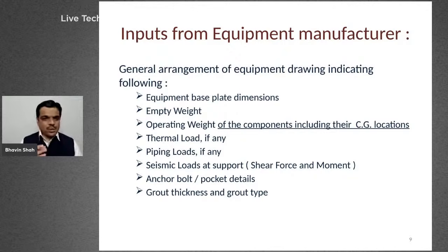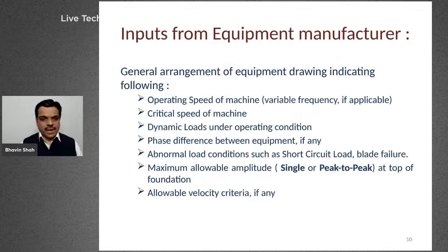And of course, grout thickness and grout type are also very important parameters that will be included in the manufacturer's drawing, and if they are not included, then we discuss with them for including them. So these were all the static load data, or general arrangement details and static load data.